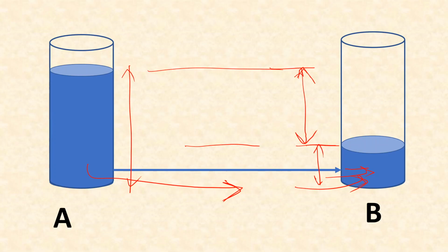You see, when water enters this tank, this velocity with which it enters, let's say it is v, can also be converted to again the head, that is v square by 2g. But in these kind of situations, we can never get that head back, and it's actually lost into the surroundings, because as soon as it enters, there will be lots of turbulence inside this tank.